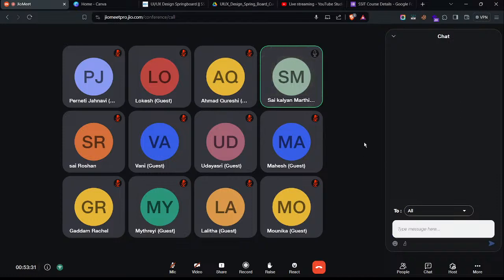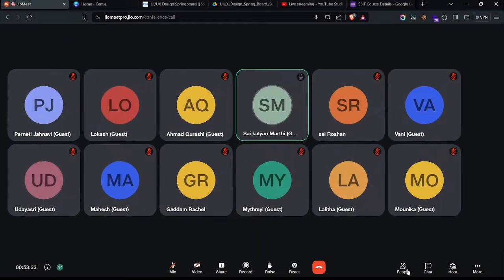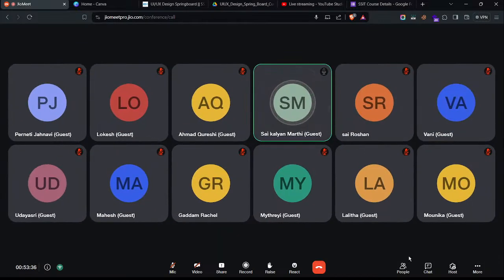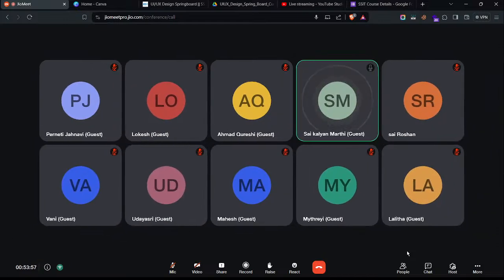While designing the hardware, what we go through are the data sheets and the application notes given by the vendor. Let us take, for example, Texas Instruments, the chipset developer. They give a data sheet or application note on how to use the schematic and how to interact with that particular chipset. Depending on that, we need to design our own hardware.